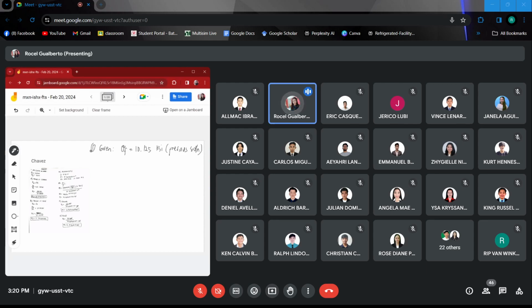So, you have here yung given, and then we go now with material specification. Okay, so material specification, we have AISI C1050 as rolled. So you find the value of sigma U and the sigma Y value, okay, and then the reference table, and the page number.